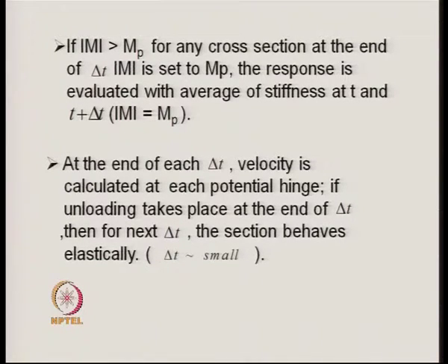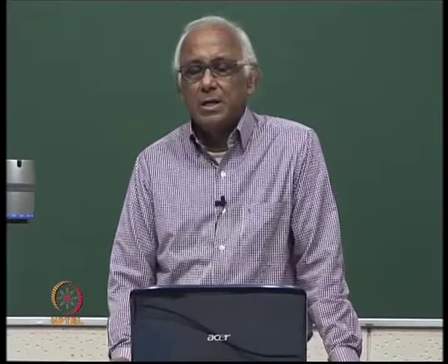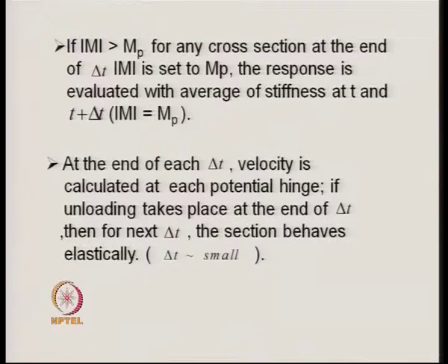If the M computed at the end of any calculation becomes equal to or greater than the plastic moment, then at the end of the delta t, we do not modify the calculation the way we had done for a two-story frame or a single story frame.